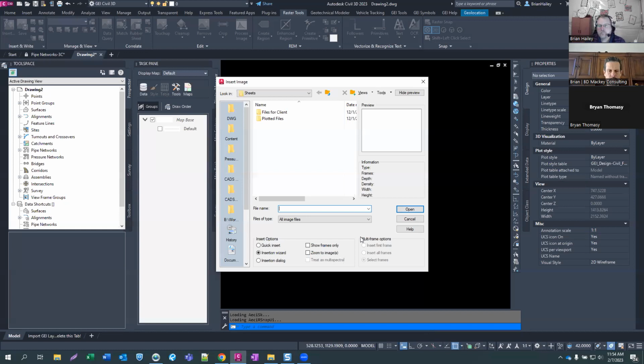And then what I'll do is I'll take a snippet from Google Earth, save it at high resolution, bring it in, choose 2 points as far away as I can that are on both images, draw a line, rotate, scale, and then put it in that fashion. So that way you just use the align command.